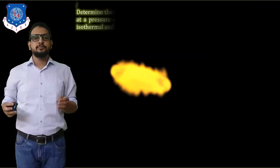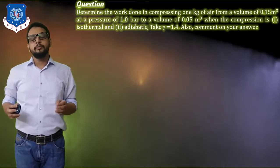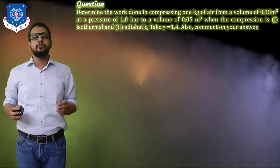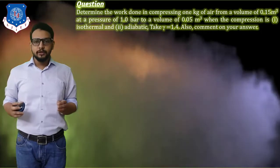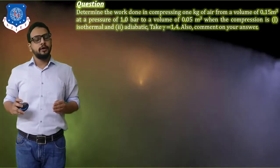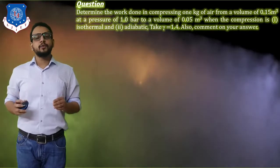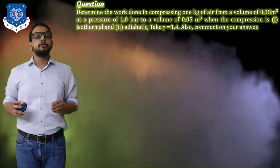Okay, so the question is displayed on the screen. Determine work done in compressing 1 kg of air from a volume of 0.15 meter cube at a pressure of 1 bar to a final volume of 0.05 meter cube when compression is first according to isothermal process and second according to adiabatic process. We need to take adiabatic index gamma equal to 1.4, and it is also given that you need to comment on your answer.